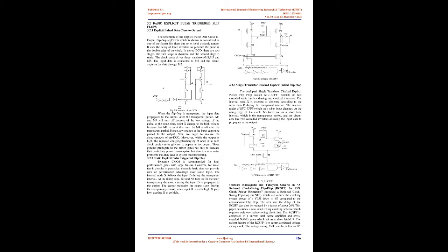SPICE analysis is carried out assuming typical parameters of a generic 0.5 µm double metal CMOS process. The delay depends on WCLK. Since delay improvement is saturated at WCLK equals 10 µm, this value of WCLK is used in the area and power estimation. The power consumption is reduced to about 1/2-1/3 compared to the conventional F/F depending on the type of the clock driver and well. In the best case studied here, 63% power reduction is observed.